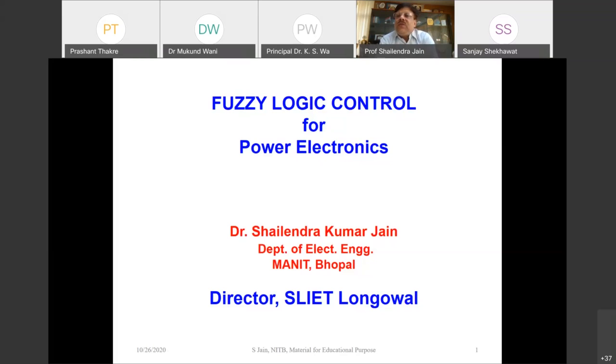Conventionally, most of our loads were in the form of motors, that too induction motors. Though they draw a reactive component of current, the current remains sinusoidal, similar to the shape of the voltage. But the moment we introduce a power electronic converter, Ohm's law is also violated.